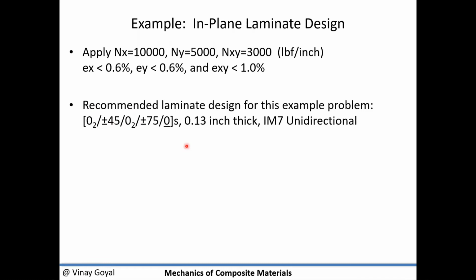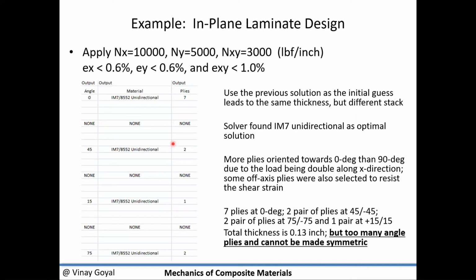I'm not seeing a significant issue with this design, but again, you should check for your problem of interest if you need to do something with sacrificial plies in case you have some sort of impact damage potential. Then you want to add a few more plies on the outside to protect the structure even more, and maybe some fiberglass.